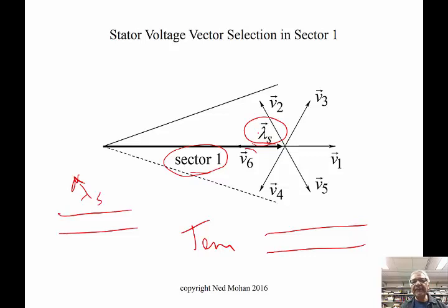So let's say, given this position here that we are assuming, these are the 6 possible active voltage vectors we can apply for this particular time step that we judiciously choose. So you can see here that applying any of these voltage space vectors for some particular time interval delta t would have certain impact.